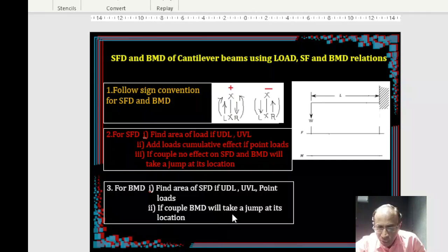If you want bending moment diagram, you take the area of the shear force diagram. Okay. So here, because it is a constant load, right? Here area in the sense, you don't even have to multiply with the distance. You can directly proceed by taking the load magnitude, because when there is a point load, the variation of the shear force is going to be constant, right?